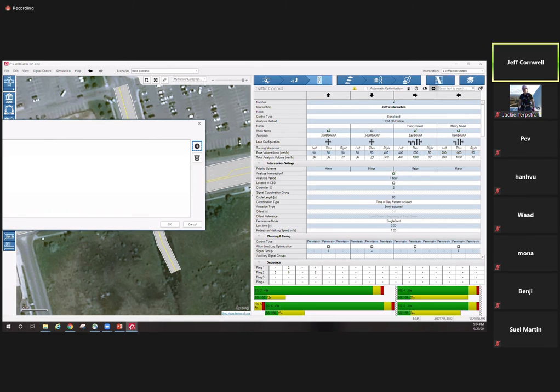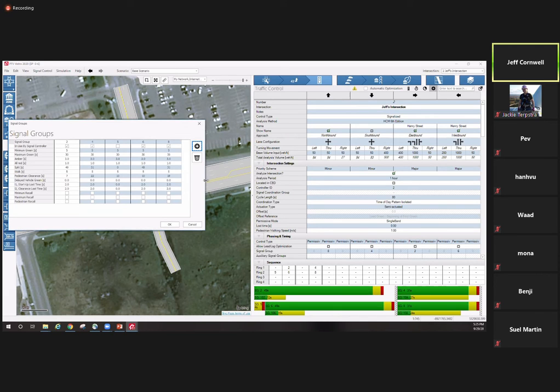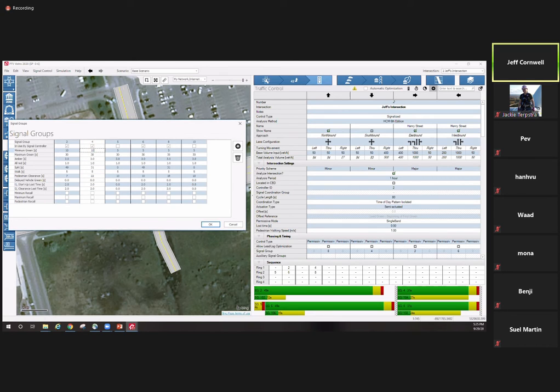Sorry, you guys probably don't have to drag it. I'm just doing this because I have 2 screens going. You can add number 1, and then you can enter times if you want. So min green would usually be 5. For phases 2, 4, 6, and 8, usually we use mins of 10. So if you wanted to, you could start filling this section out. 10, 10, 10, 10.